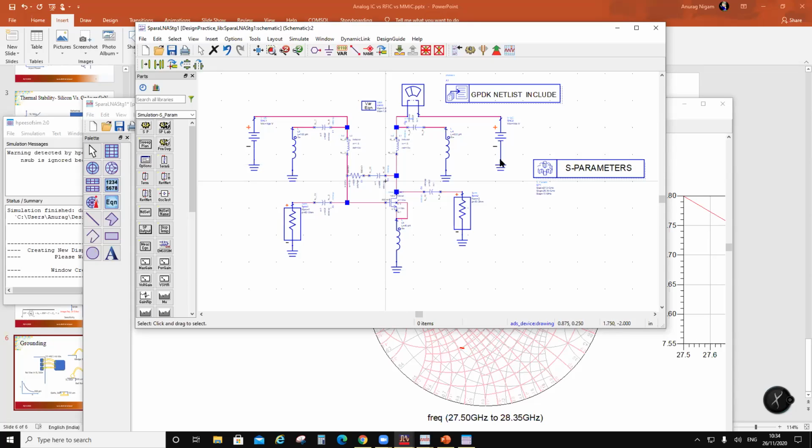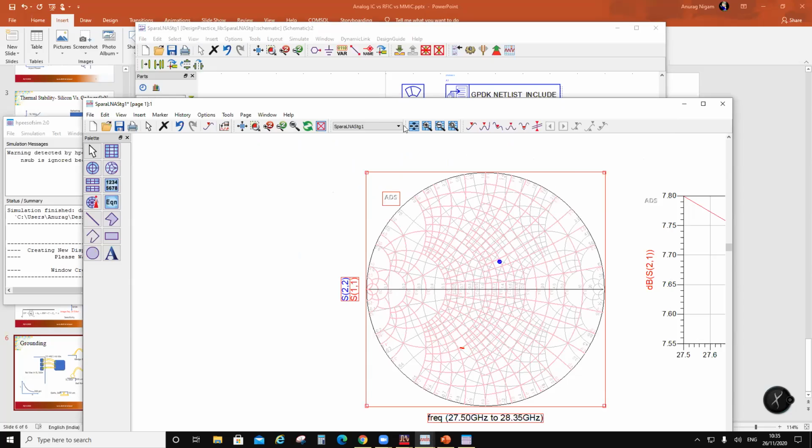Okay, in the books, this is not there. None of the authors is telling you this, that I need a very good short. That's why I have a radial stub and a line. But you go by the convention: MMIC has to be done with a stub, RFIC, I'll use the capacitor. No, that's not the story. The story is I need a very good short here. That's why I would put two capacitors here to reduce the equivalent series resistance. Okay, so that's the point in here.